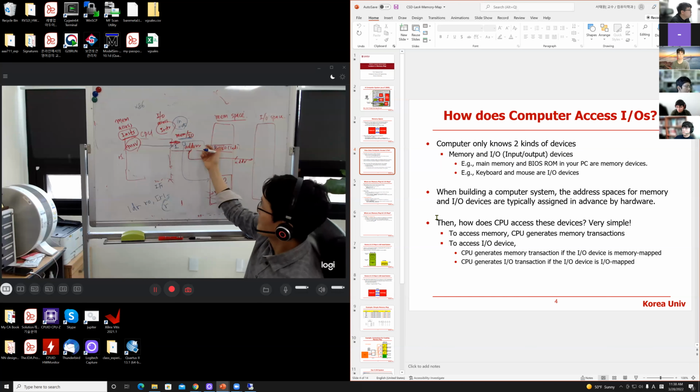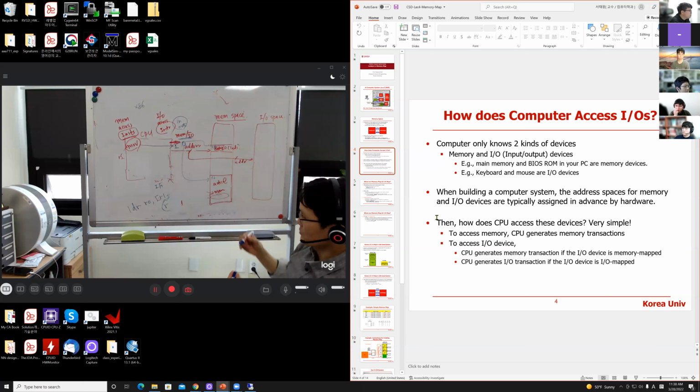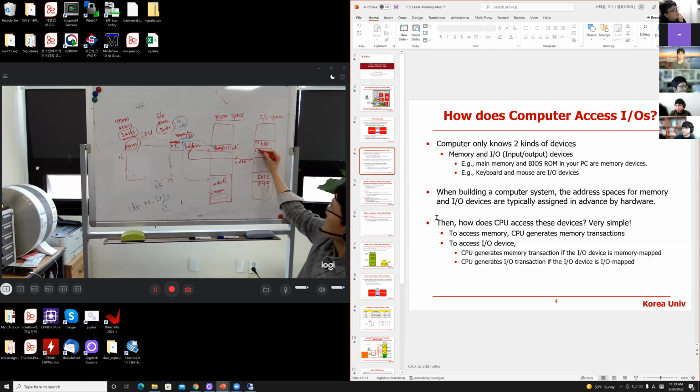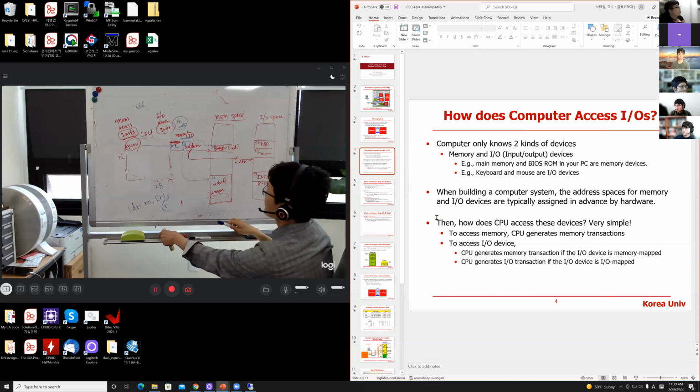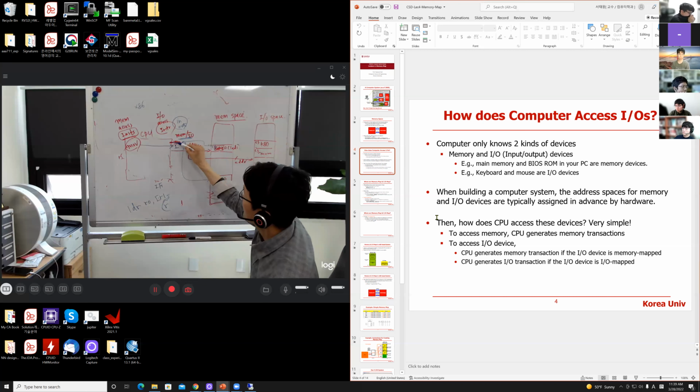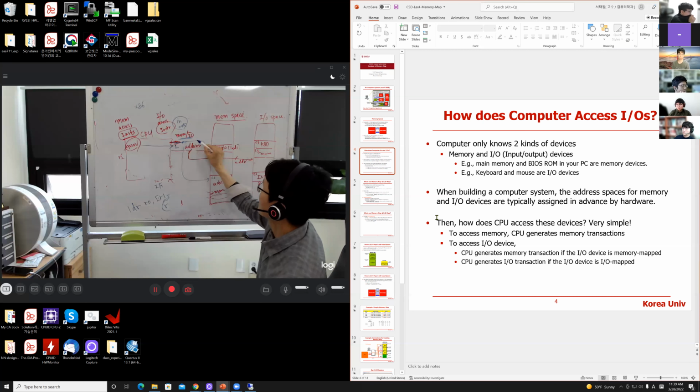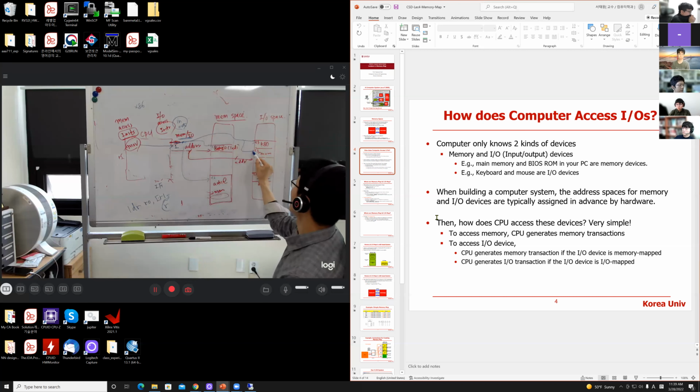IO access is active. So then how to make the connection? Assume that you have a keyboard here, a mouse, and some legacy interrupt controller, very old, 8259. Then you have chip select, and you have to make a connection, right? You have one output, and somehow you want to connect that to the chip select, like this. But you have to be careful.